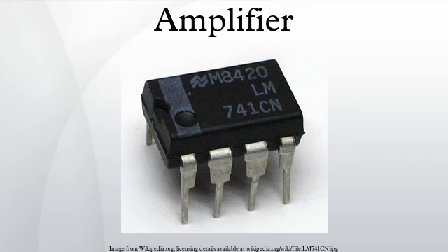In Class AB operation, each device operates the same way as in Class B over half the waveform, but also conducts a small amount on the other half. As a result, the region where both devices simultaneously are nearly off is reduced. The result is that when the waveforms from the two devices are combined, the crossover is greatly minimized or eliminated altogether. The exact choice of quiescent current, the standing current through both devices when there is no signal, makes a large difference to the level of distortion.